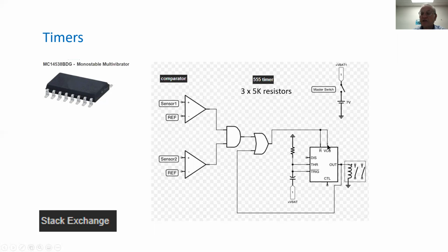And the way the timer is triggered, as soon as the trigger sets an output 1 here, this is going to continue the process. This is a set. The trigger, which normally grounds the voltage across the capacitor, is now going to cut it off, and the voltage, which is going to be set here by a master switch into the capacitor, is going to let the capacitor start charging.